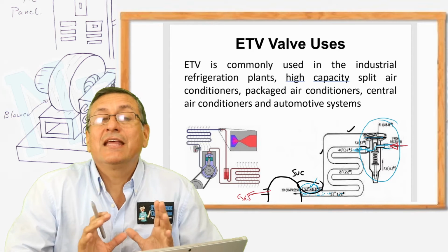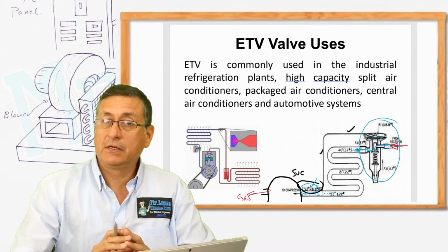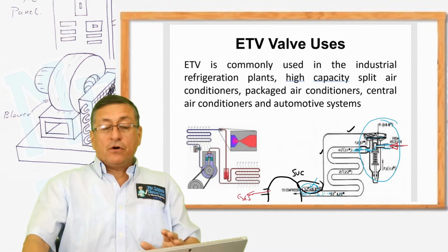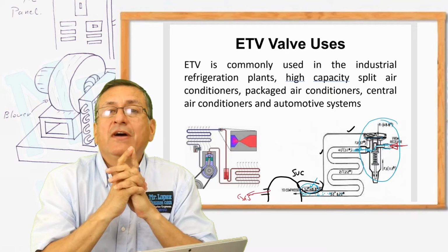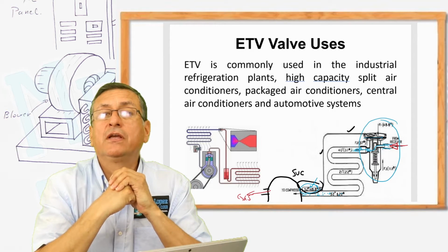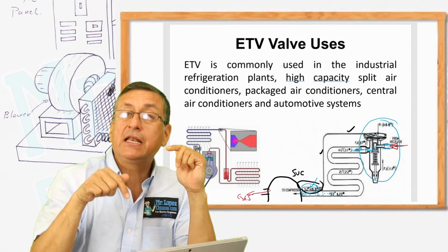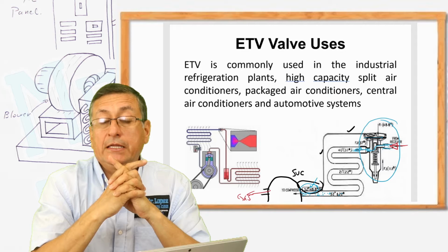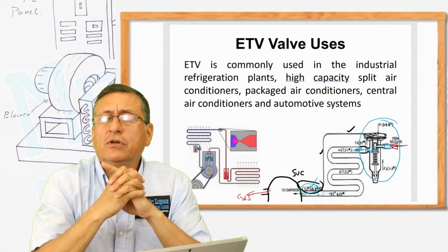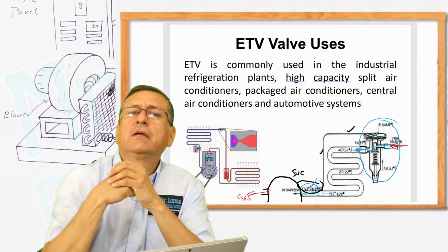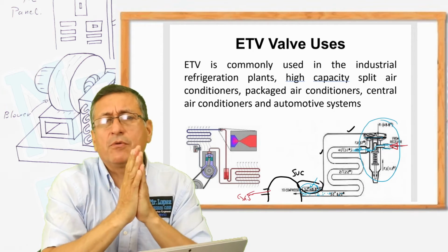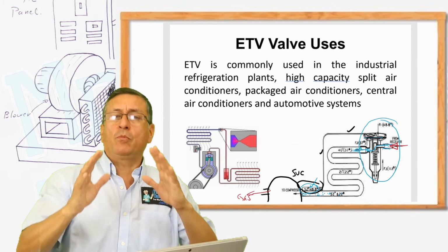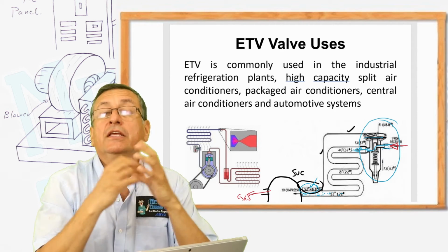Yes, it's clear. This is the operation of the thermal expansion valve. It's pretty simple. Don't forget, in terms of expansion valves, we have capillary pipe expansion valves, or we have a thermal expansion valve like this one that I explained right now and in the video clip. There are other types of adjustable thermal expansion valves for industrial application, but for marine application, those are the expansion valves that we are going to use commonly in this course.